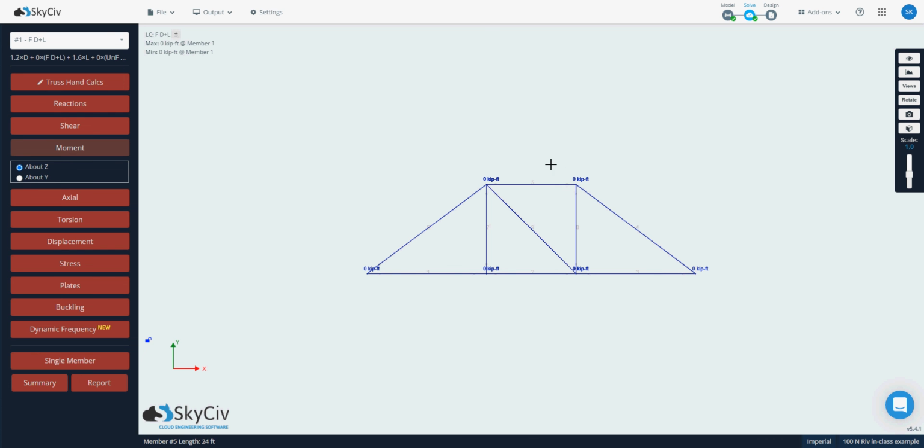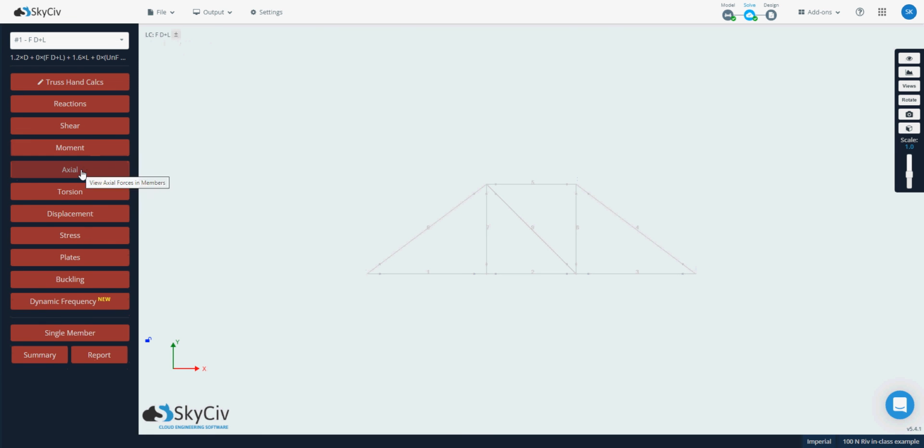Now, as soon as I would start loading a truss, let's say I have a point load coming down right here in the middle of this member, you'll start getting moments. Let's say in member 5, or same thing, if I put a force here, you'll get a moment in this piece. So if we load the truss only at the panel points, we only get axial loads within the truss. Okay, so it's moments we don't want. We want axial loads. Okay.